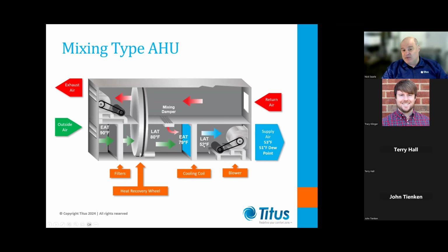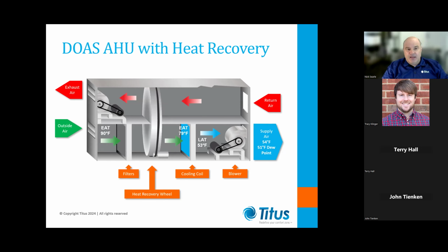Ideally, you may be wanting to drop a little bit below 52. But for this setup that I'm showing here, for most designs, you'd probably want to be designing the office building at around 53 RH to get away with that. Now, you could use a DOAS for some applications, maybe a school application. So this is the kind of setup that you use there.